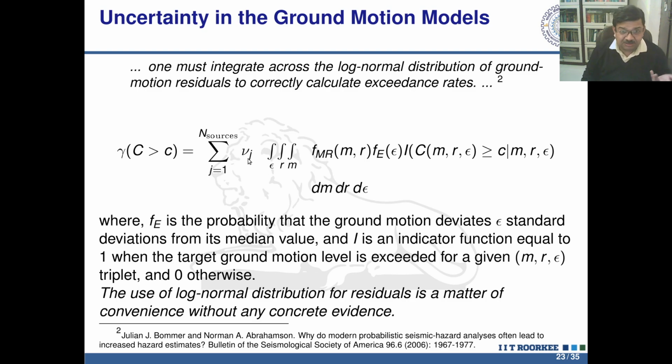Which algorithm is a rational algorithm? It is all kind of a data fitting exercise. Some earthquake happens, some data suits the Poisson distribution model. It is recommended to be used, and that same model fails in some other earthquake. So it is not really a very scientific way of declustering. So how to compute this seismicity rate? Nobody knows what the exact seismicity rate is.